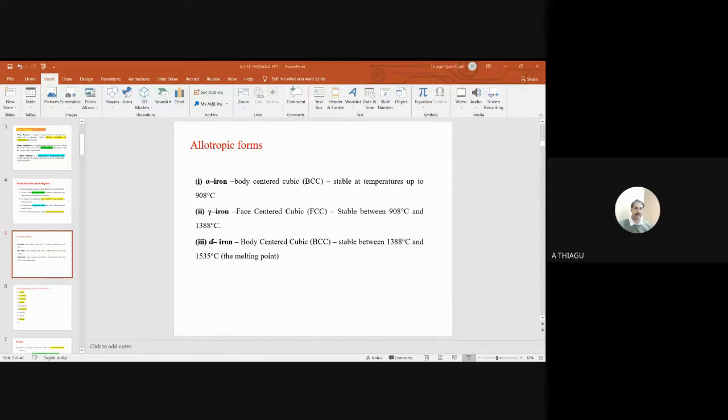Cast iron is differentiated from steel because a higher percentage of carbon is involved, 2.14 to 6.67, but practically they won't go beyond 4.7 weight percentage of carbon. So please understand the range of carbon for different materials. Sometimes they frame the question based upon the weight percentage of carbon.